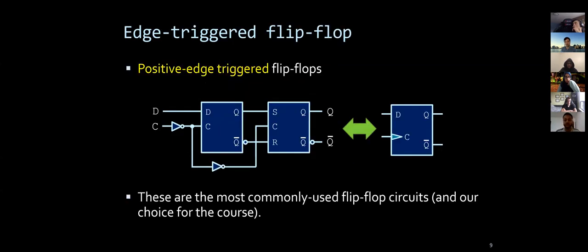And at the end of the day, we were building flip-flops, right, with all these different latches. So combining the SR latch with the D latch, we can get something that is going to flip properly, right? So it can flip on the positive edge or the negative edge. So what does it mean, flipping on the positive or negative edge? Positive edge means when I go from signal 0 to high power, right? That counts, it means it's positive. We're going from 0 to like 5 volts. And if you go from high to low, that's a negative-edge triggered flip-flop.